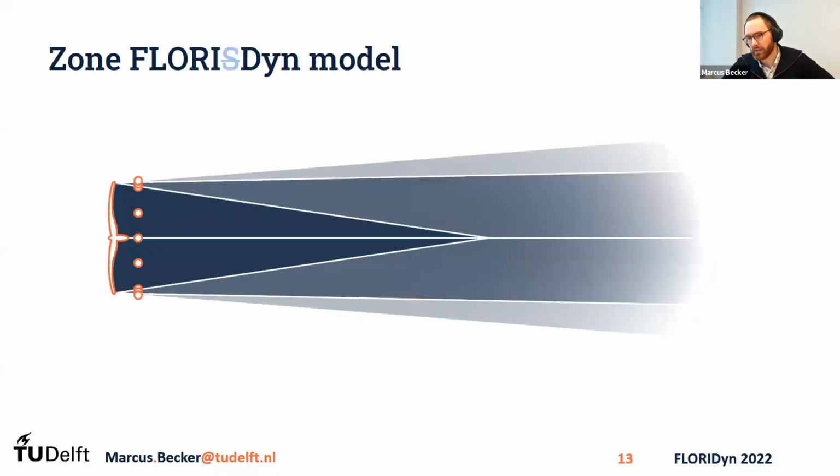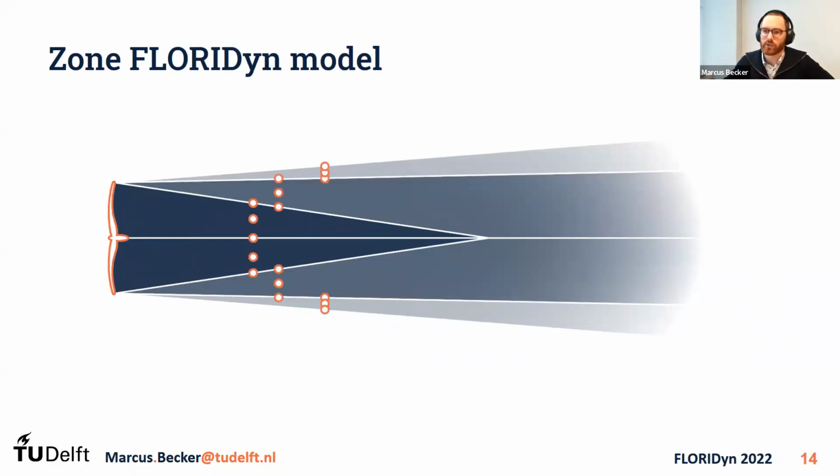So our idea is that every time step, we're going to create little traces called observation points. And these observation points are going to travel along the edges of the zones we have defined in the model. And since our computation is so easy, we can just let them run downstream based on only the state of the turbine at the time when they were created, a set of parameters describing the wake, and then their own downwind distance, which increases over time as they travel with the wind.